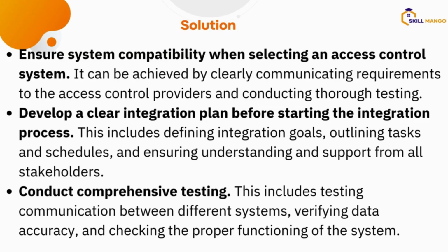I want to achieve intrusion detection. I want to achieve automatic capturing of whoever swipes their card or flashes their card or uses their biometric at my door. You have to know what you want to integrate and what you want to achieve with your cameras and your access control. What do you want to achieve? You have to design and specify. So you now start looking for the best product that will achieve those functions for you.